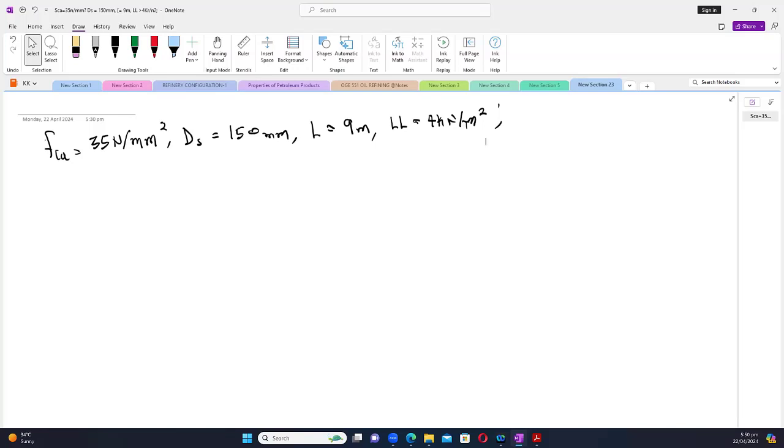Could be there for years, and the load is not like an occupancy load. Like today, I'm in the office, I'm not at home, so my load is not there. So hardly does it vary, I mean the partition loads. It will only vary when, for some reason, there's some service works or some renovation. That is when it will be gone. But realistically, most of the time, oftentimes, it will be there as a permanent load. For that reason, we are going to make the partition load a dead load. Okay, so we have a dead load from partition.